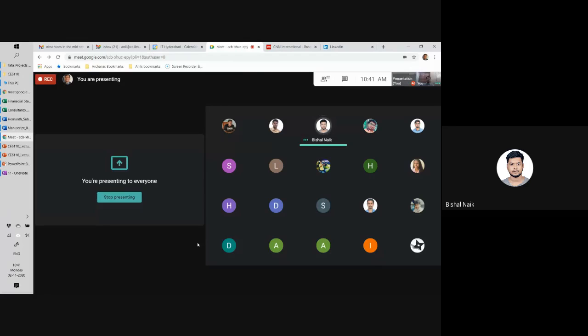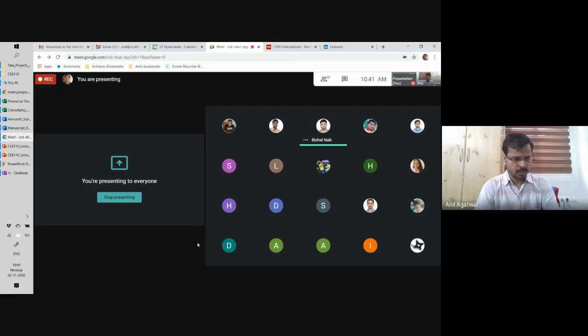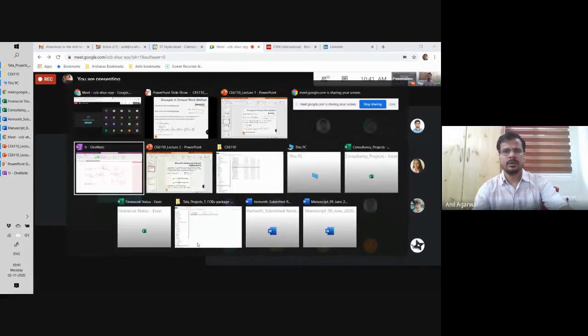Sir, basically, what we do is we apply a virtual load, a load that does not actually exist on the member. For that virtual load, we get some internal work, and that should be equal to the external work due to the displacement in the member. Yes, in general, what you have said is correct, Vishal. Maybe I can just expand it a little for everybody's interest.